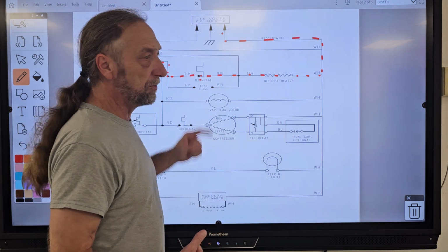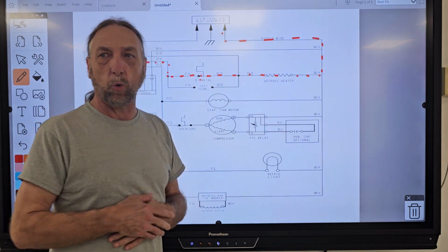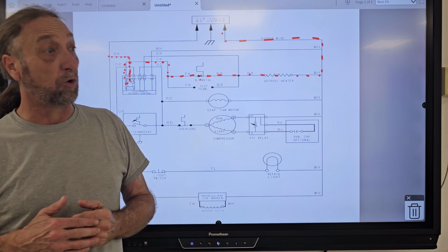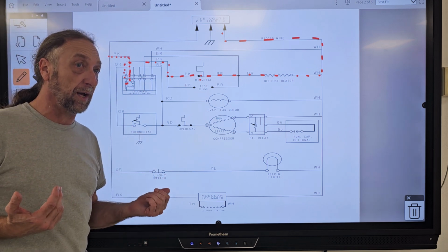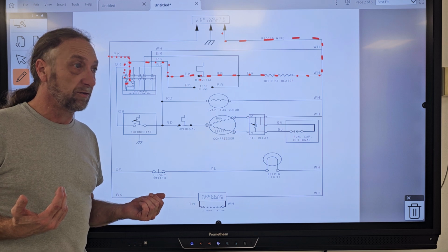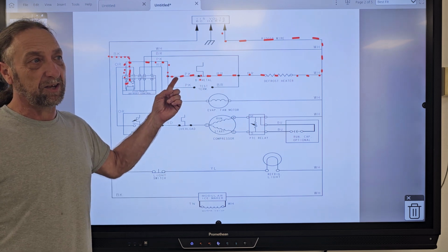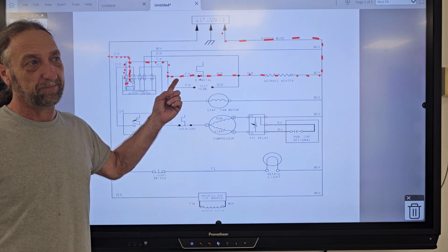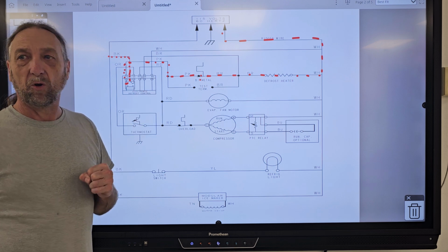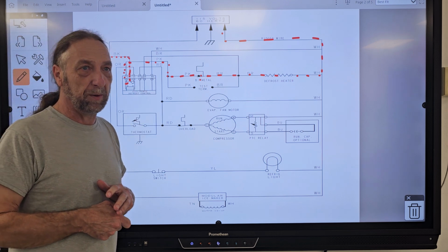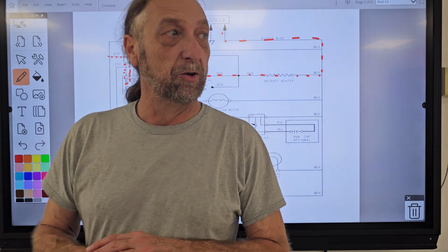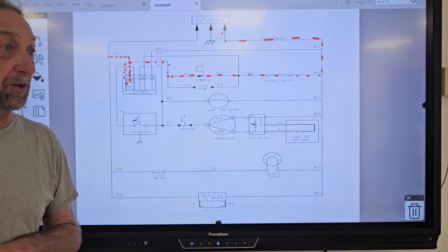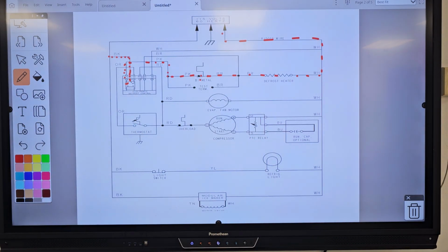What closes that thermostat? When it's hot or when it's cold? When it's cold. But in order to get the panel off, I gotta melt all the ice, right? So once I start adding heat, that's going to open up on me. So that's not where I put my meter to make my test. Where do I put my meter? I know you know it, you just don't want to say it, because we had this discussion.